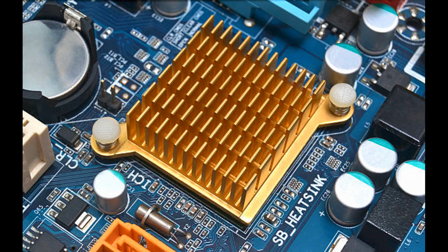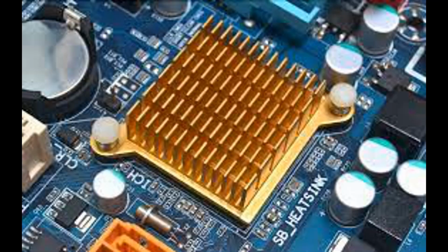Here's how a thermoelectric heatsink operates. Cooling mode: in cooling mode, an electric current is passed through the thermoelectric module, causing heat to be absorbed from the heat source at the cold side. This absorbed heat is then transferred to the hot side, where it is dissipated into the surrounding environment using a conventional heatsink or cooling fan. Heating mode: in heating mode, the direction of the electric current is reversed, causing heat to be absorbed from the surrounding environment at the cold side and released at the hot side. This allows the thermoelectric heatsink to provide heating as well as cooling capabilities.